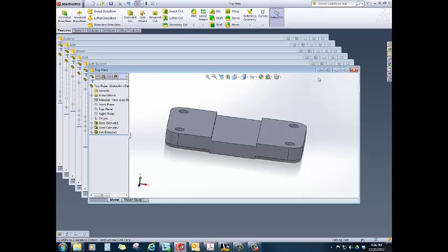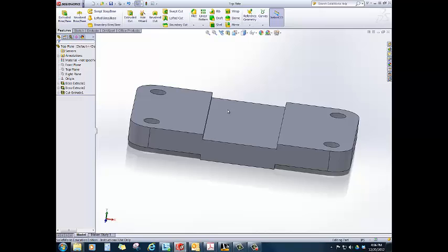We'll then begin again with this top plate, so then maximize that back out. And from here I'm ready to create my assembly drawing. Now because I have all the files open, I'm going to be able to skip several steps involved in the process. To begin the assembly drawing, I need to move up to the New folder. That can be done with the Control N key on your keypad if you're into hotkeys, or I can hit the pull down menu and simply select Make Assembly from Part/Assembly.